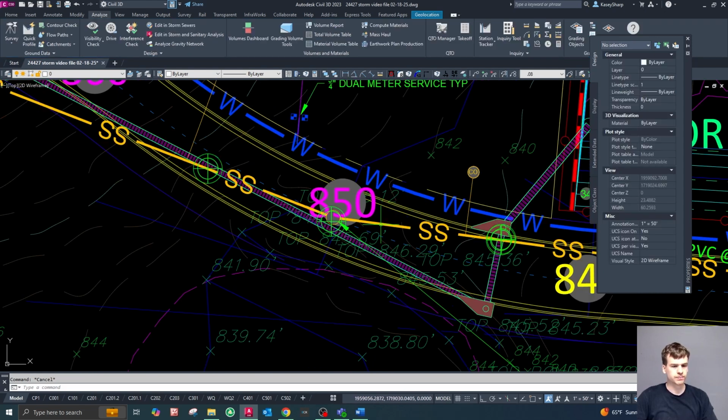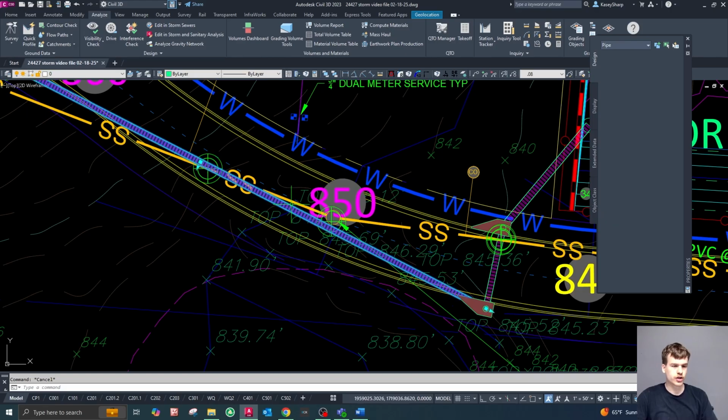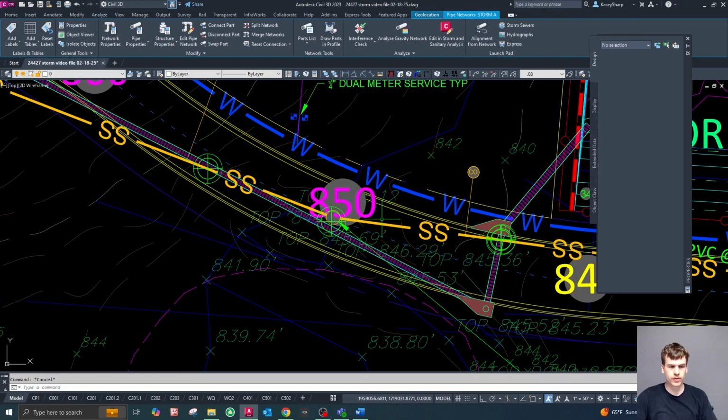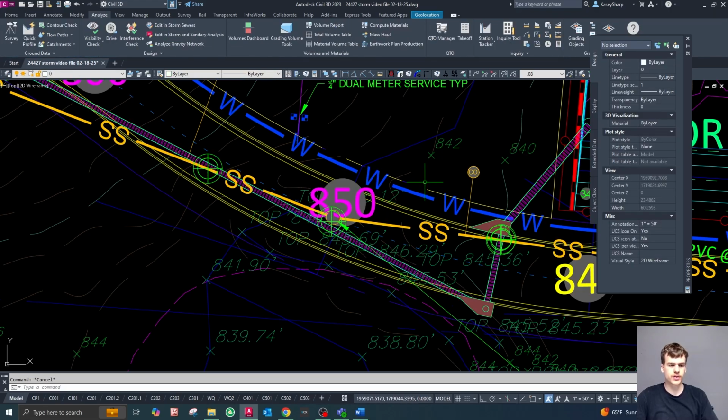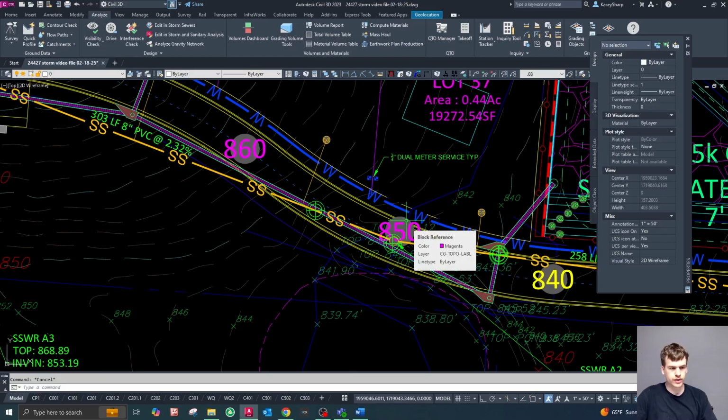So we're not going to go through and fix all the inverts now. That's a pretty self-explanatory process. We're going to go ahead and adjust the inverts here of both your sanitary sewer and your stormwater pipes such that they don't interfere. You can go back and watch the videos on the creation of pipe networks for sanitary sewer and stormwater networks to know how to adjust the inverts. You're just going to make those changes such that they don't interfere.